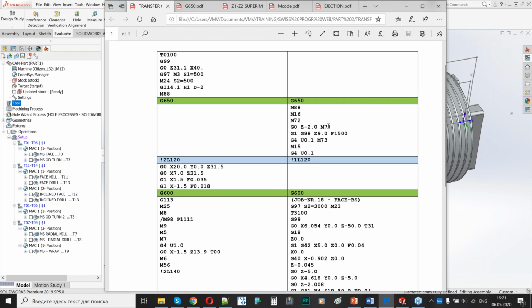It is a command called wait until spindle synchronization is complete. So machine needs time to synchronize the spindle speed, and this code is needed to check if the second spindle reached the speed of the first spindle. It's like a safety code, because some machines which do not have this code are using an additional dwell here.